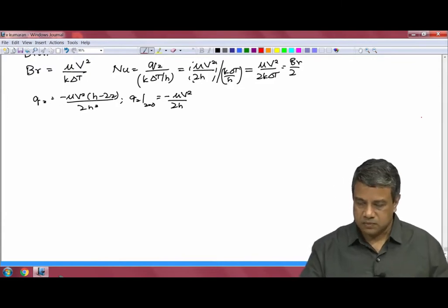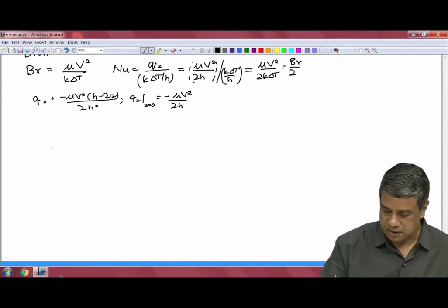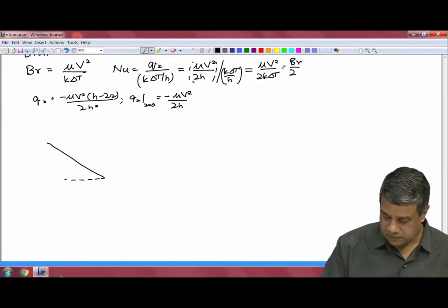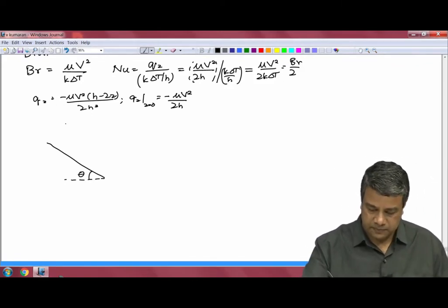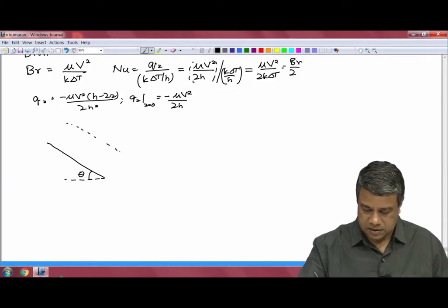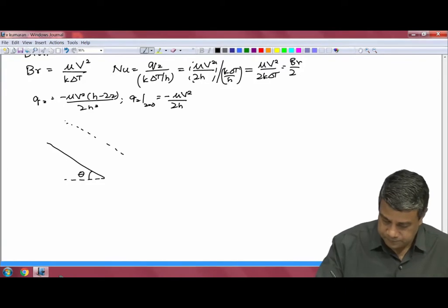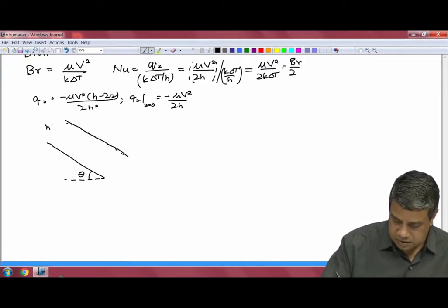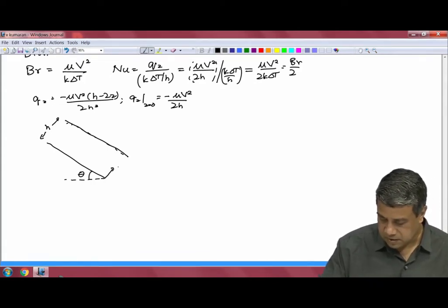Let us consider one more case where the source is a constant. This particular case is the flow down an inclined plane, a flow down a plane inclined at an angle theta to the horizontal. We will assume that the flow is at steady state, with film thickness h. I will take the cross stream coordinate as z, and the streamwise coordinate as x.